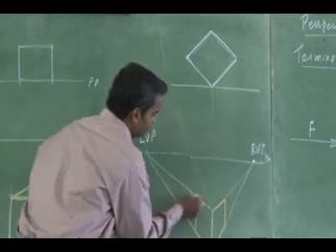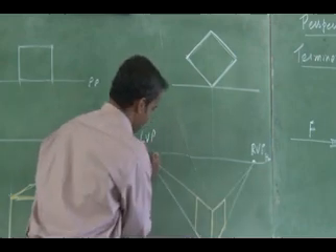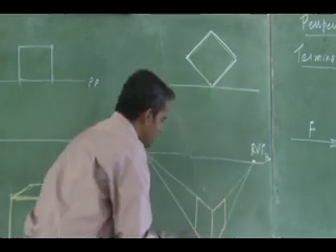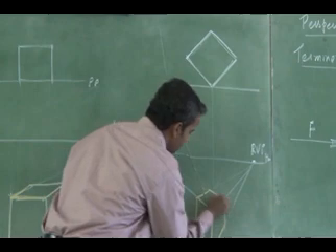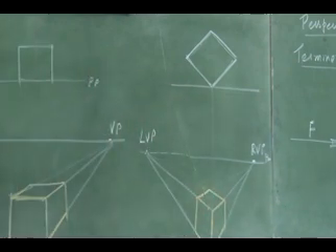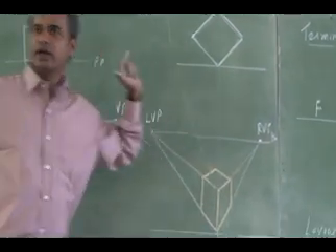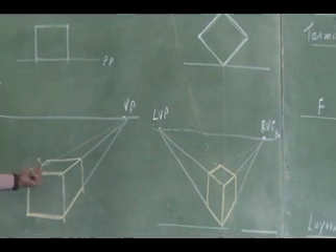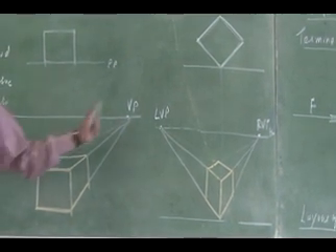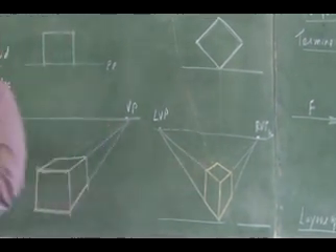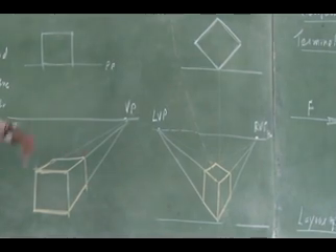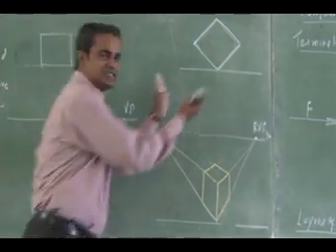Now the perspective view is more realistic than this. If it is an inclined surface, the same is a 2-point perspective. The same thing I can draw in single point perspective itself, but to represent it in a more realistic manner, I have to go for a 2-point perspective if two faces are inclined.